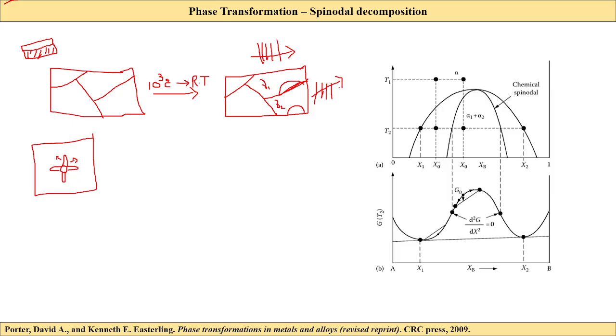So again, we have discussed the low angle and high angle. Depending upon the orientation we have tilt axis and twist axis, right? So there are low angle grain boundaries, high angle grain boundaries, and special angle grain boundaries, which we call twin boundaries. All these things we have discussed, you can go and check them in those lectures, right? So what is happening in heterogeneous nucleation?